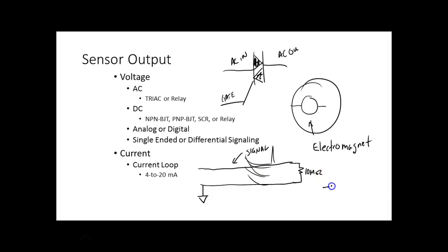But if I came over here and used current in a current loop and don't use a ground reference, then this guy here might be 10 ohms. Now when the EMI comes into this, the voltage it tries to put into it would not be, it's like static electricity. So static electricity, how much work can you get out of static electricity?